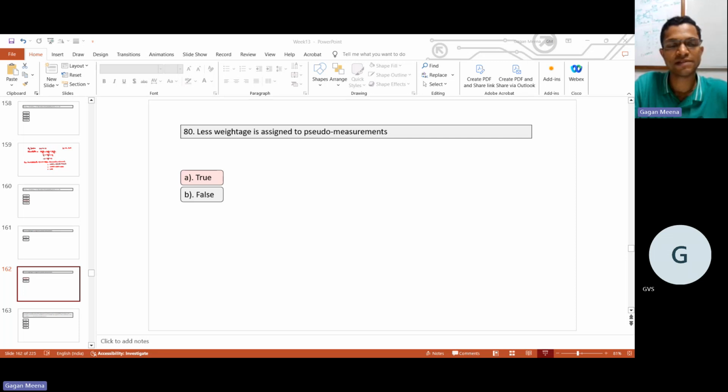This is the permissible synchronizing error for a PMU for 60 Hz: it is 0.0216 degrees. Class P PMU does not have anti-aliasing.